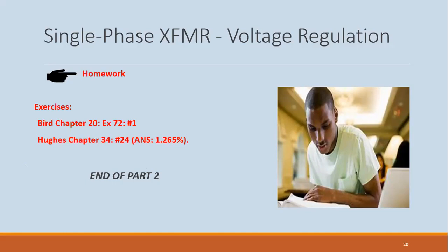One of the ways would be to use the tests that we would have done in the lab, the open circuit and short circuit tests. By the way, those tests can also help us to calculate the voltage regulation. So you will get those lab data later on in the semester.